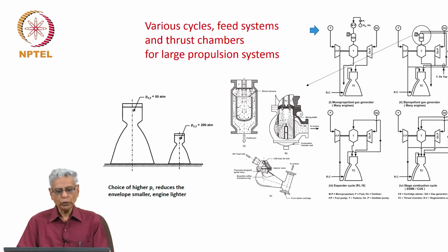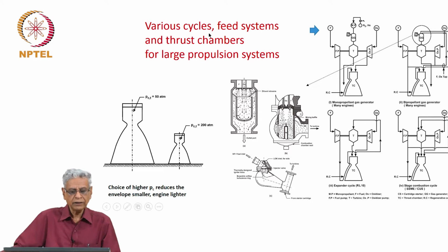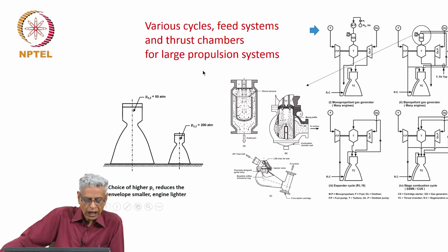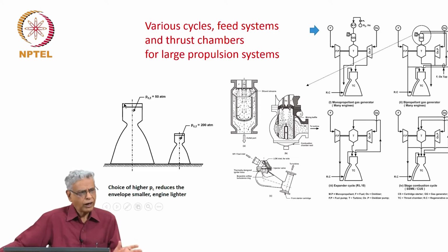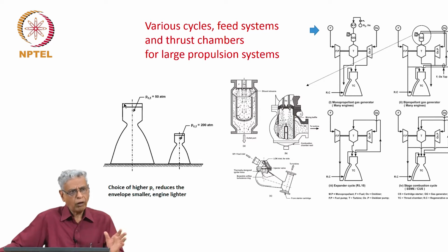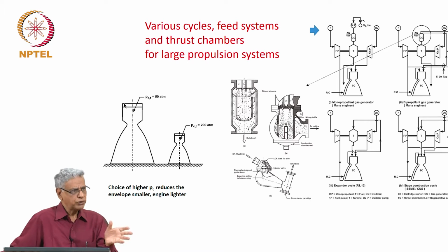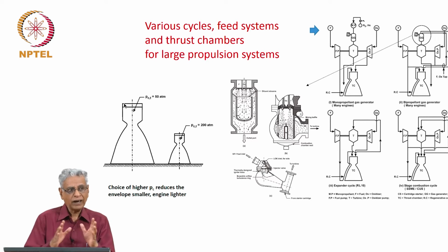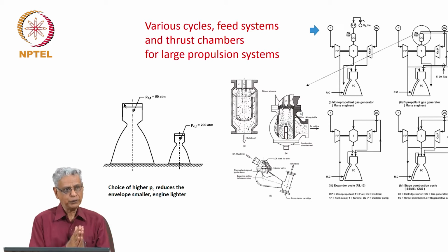Let us shift to various cycles, feed systems, thrust chambers for large propulsion systems. One key point I want to make to you is the following. Rocket operating conditions are always at high pressure, but the question is what pressure is good and what pressure is not good. In comparison to solid rockets, the liquid rockets have a certain advantage.